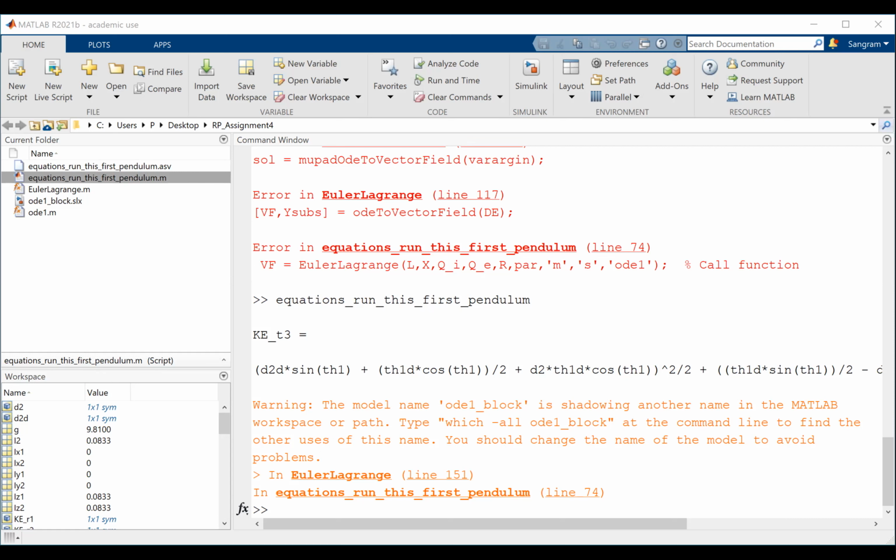So if you want that robot to go from point A to point B and extend, what you would do is you would add a torque here and then you would add a force here so that the robot can rotate and the robot can extend. Everyone understood this? So this is the joint torque for joint 1. This is the joint force because the second joint is a prismatic joint. It cannot have torque, it can have force. Torque on the first joint, force on the second joint. Everyone understood this? And finally, you have the R, which is the energy dissipated and damping.